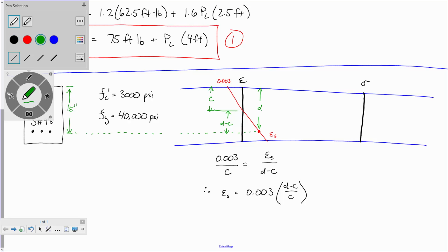So if I take this neutral axis, that's c, sort of extend it on, so that's my neutral axis line right there. If I take my c distance and extend it, I see no effect from the concrete below. The only force that I see on the bottom is this tensile force right there, which for singly reinforced beams, I can assume that force has yielded, but then again, they have to yield because the strain in the steel has to be greater than 0.004, if you remember, so it has to yield.